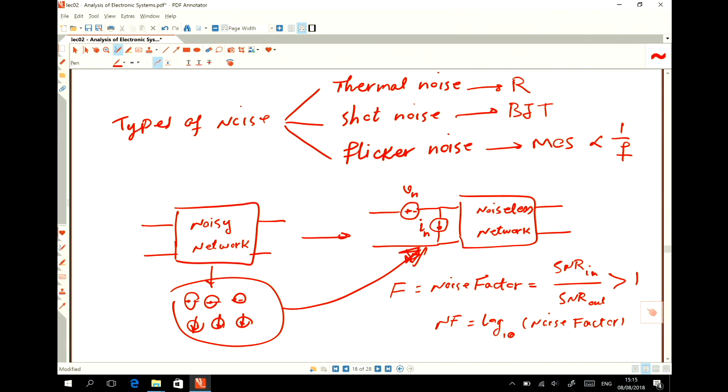The next thing was the amplifier. As an amplifier is a combination of lots of transistors and components, they usually give you two values, Vn and In, for the amplifier, the op amp. And then they say that the input referred noise Vn is this value in nanovolt over square root of hertz, and In, for example, picoampere over square root of hertz, and then you need to calculate the noise figure of the system that you biased. The first example will go for this.